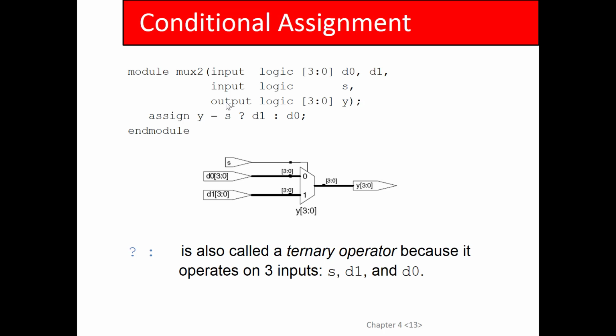So it's the same thing. I use it in C++. I don't know if they teach it in 145, 146. They teach this? No. Okay, I just use it on my own. It's a very common thing, but for some reason it's kind of obscure in the introductory programming classes. In Verilog, it's critical though, because it's the only way that you can put conditional behavior in an assignment statement, because you can't put if statements outside of an always block, which I'll get to in a minute.